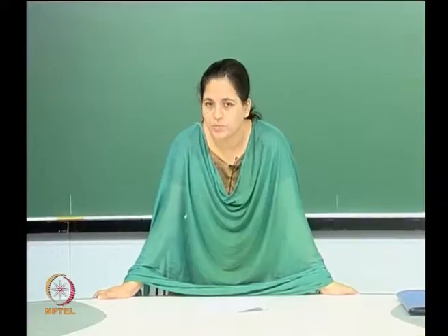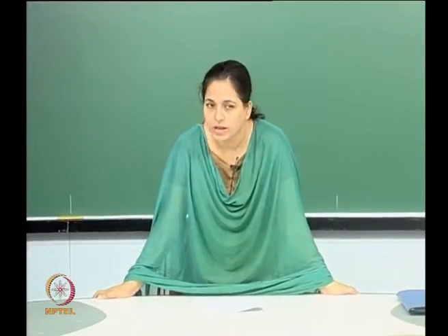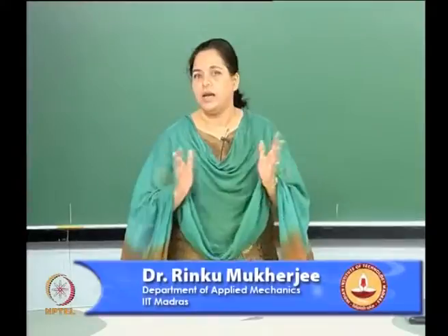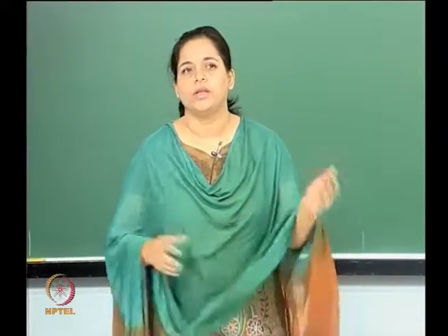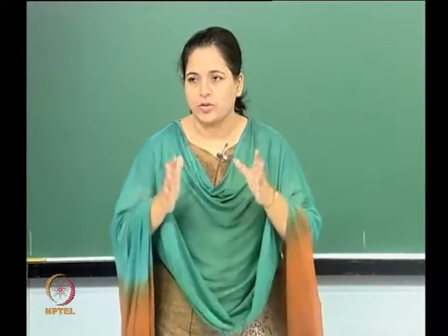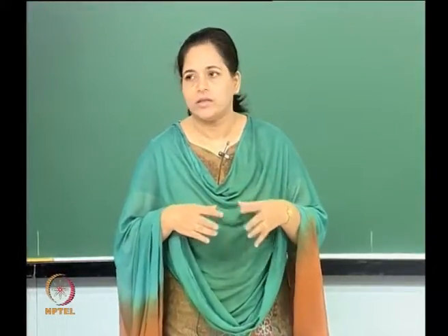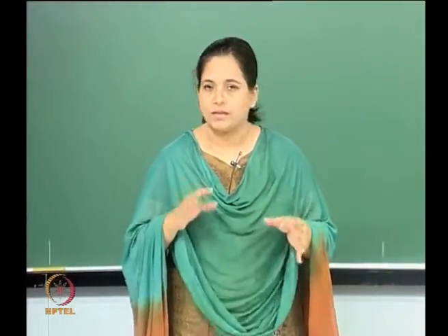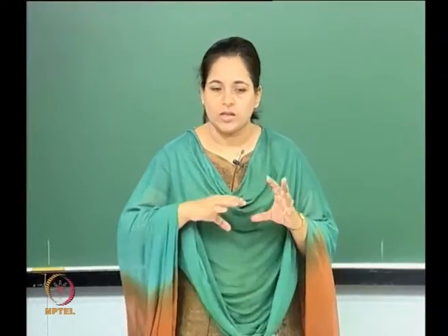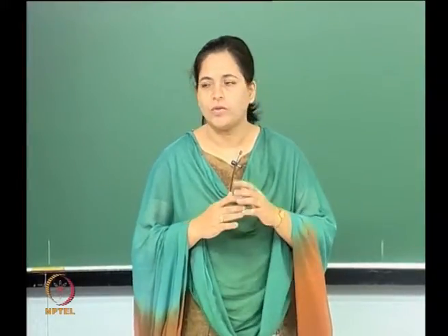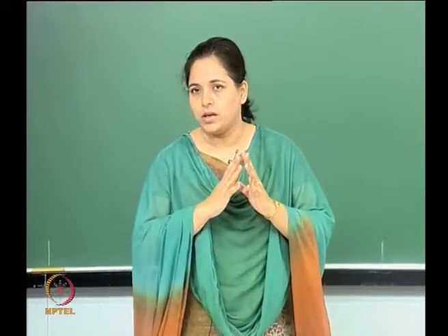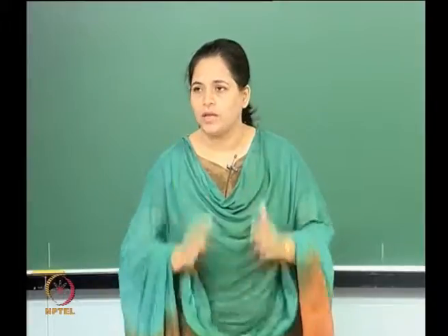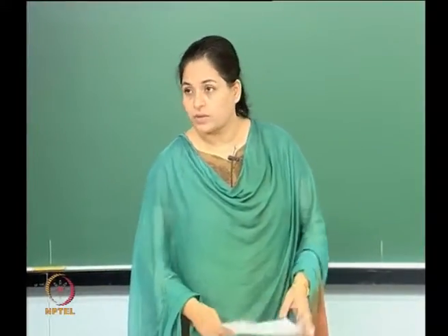That is, when the flow comes into the throat area, which is the sonic area, then it expands. And this expansion could be over a length, as it is in wind tunnels, but then we decrease that length to a point so that we have a centered expansion wave. That's really the minimum length you need, so that the flow diverges and then finally we get uniform parallel flow to the walls of the nozzle. So that's where we were.